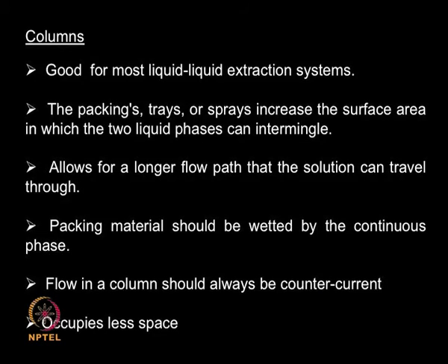So I can use packings, I can use trays, thereby I can increase the surface area of contact between the two liquids, so that the two liquids intermingle nicely. So by putting in packings, I am increasing the flow path of the solution, so the solution will travel through the interstices or spaces in the packing, so they are coming in contact with the other liquid. So I am increasing the flow path.